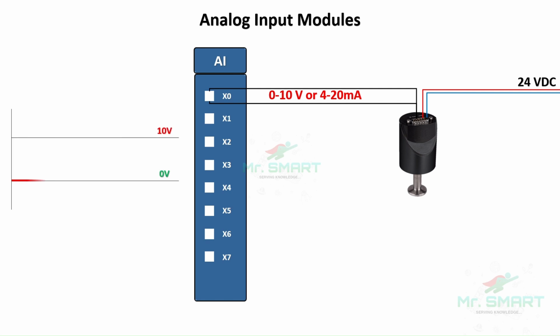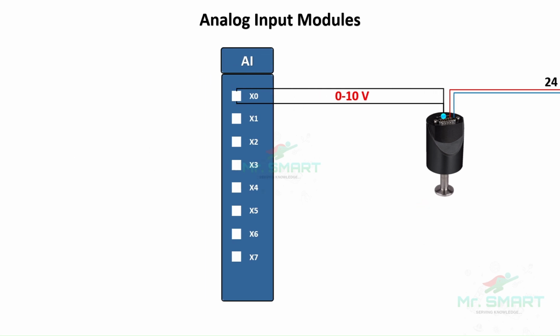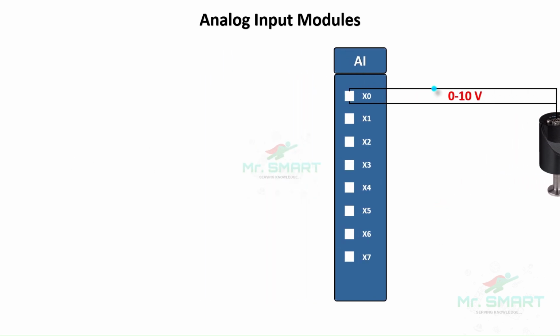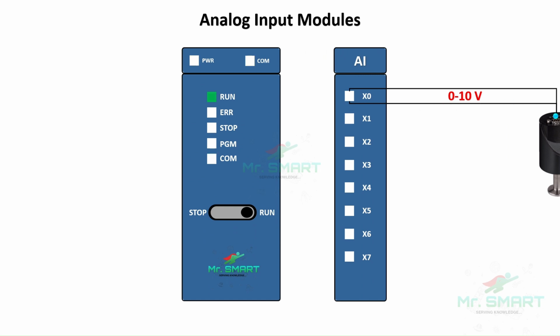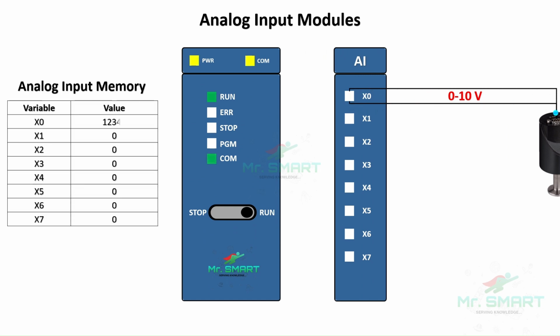Until the pressure measurement is started, it produces no current flow with the input module. When the sensor senses the pressure change, it generates output analog signals. This change in voltage is recorded to the PLC memory respective to the input port, either in the form of decimal or hexadecimal values. This value is processed by the CPU for making output decisions.